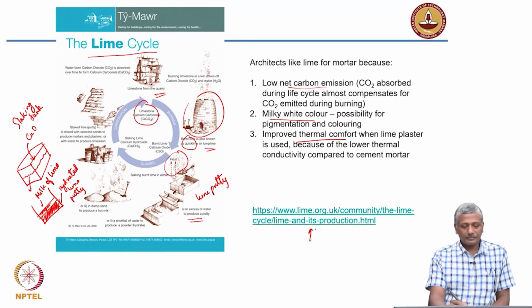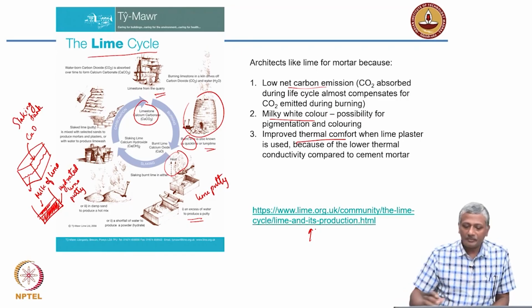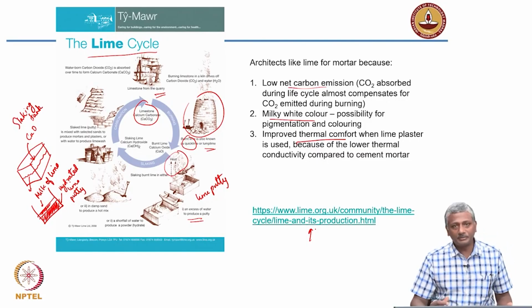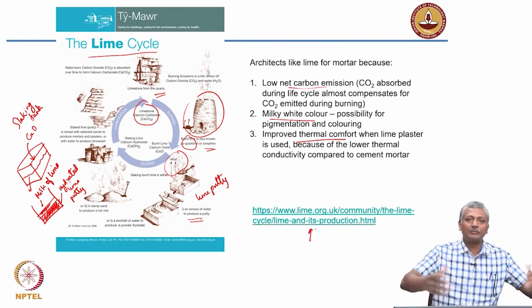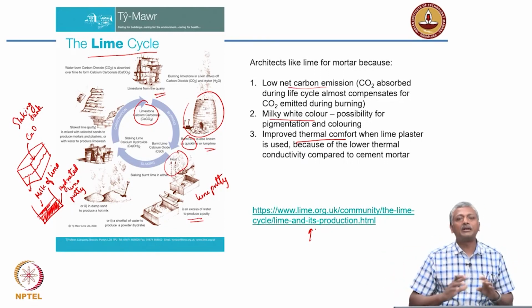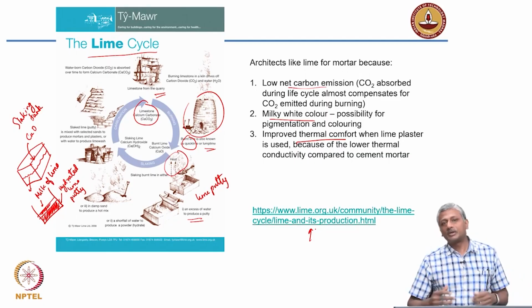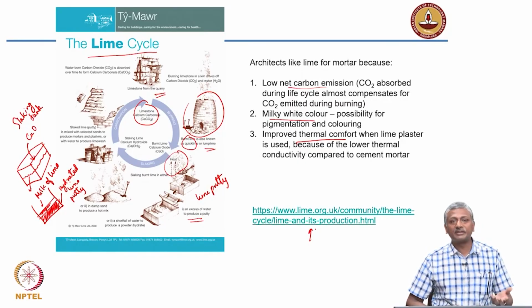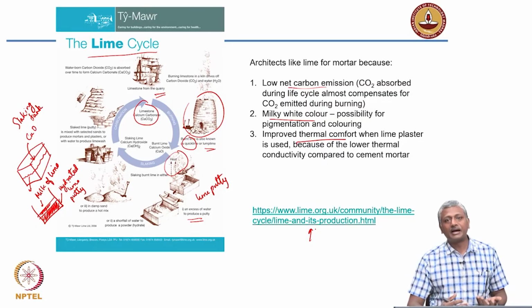Now, not all slaking practices are perfectly optimal. In some cases, people just dump the lime on the floor, mix the water into it and continuously mix it for a long time until all the heat dissipates. So it depends on how the lime slaking practice is done at the site. Once you mix it up with sand and make the mortar, it has to be in the hydrated lime form.